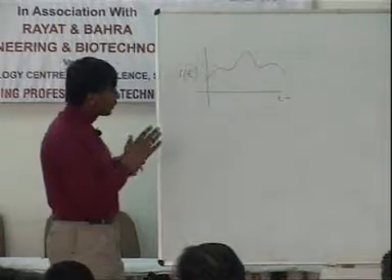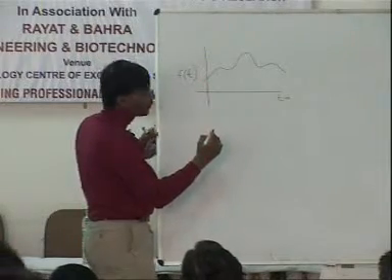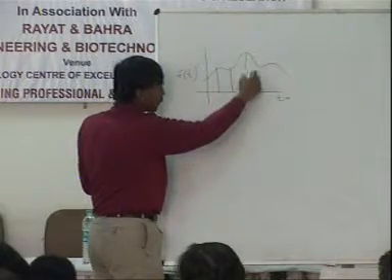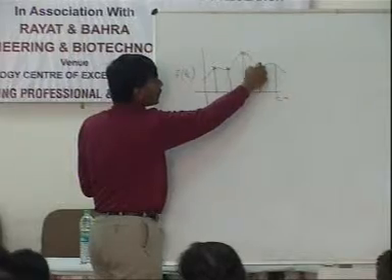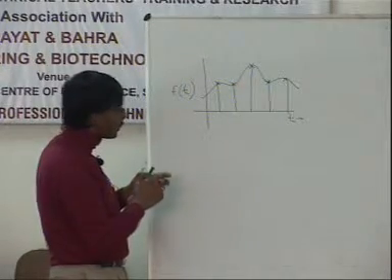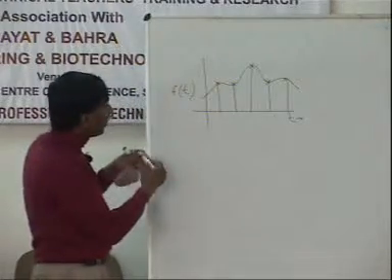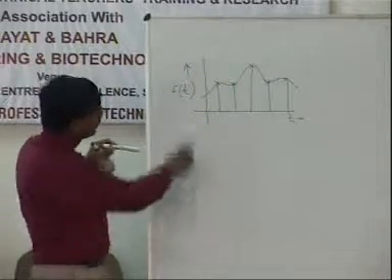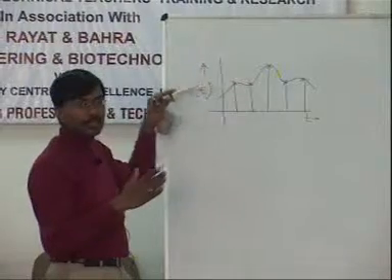Now the idea is that to go from the analog world, the world around us is analog, to the digital world, what we are doing is we are taking snapshots of the analog world at, for example, if it is a one-dimensional signal, different points in time. We are also doing a quantization in two axes. One is along the independent variable. We are also quantizing our values along the other axis, which is that of the dependent variable. And if we represent these using bits, we get a digital representation of a function or a signal.